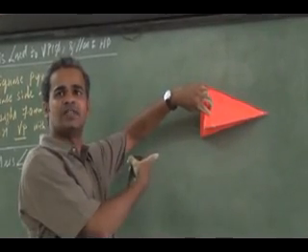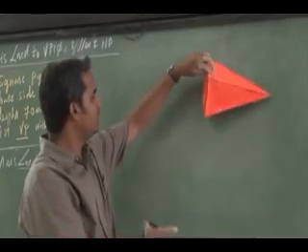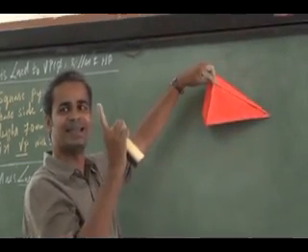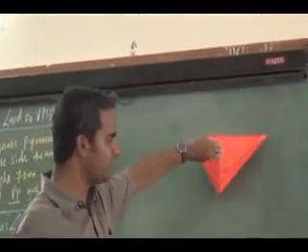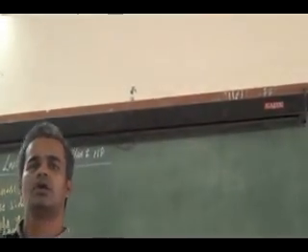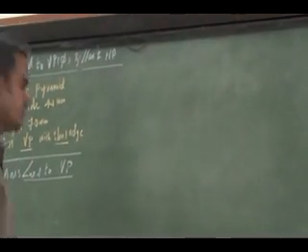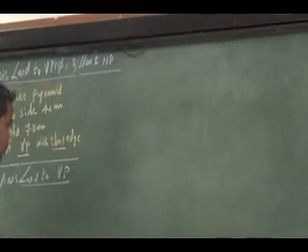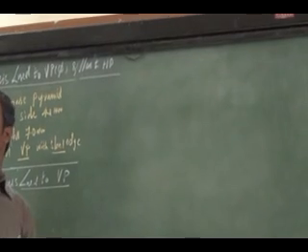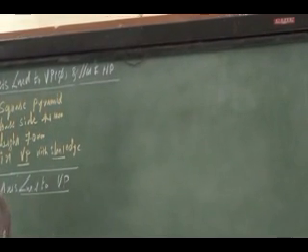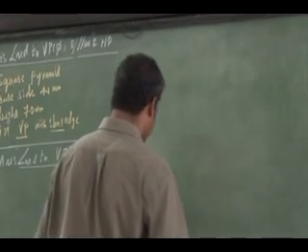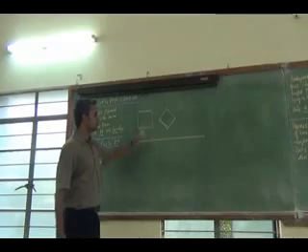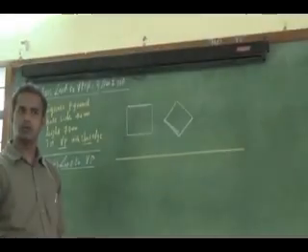So instead of lying with a slant face, I am using it lying with a slant edge. Right. So if it is lying on a slant face, that also similarly the axis is inclined to VP problem. So axis is inclined to VP. So where do I have to draw the base? On VP. So one more thing, on VP you have to draw it. First orientation, is it right?